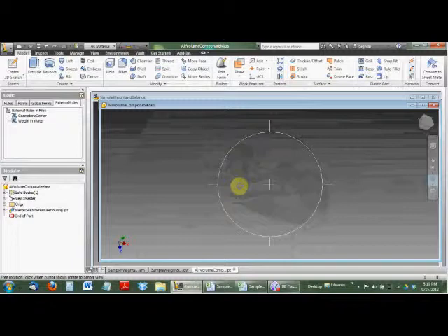And what you do is you have a model of your electronics and your chassis, you have a part model of your cylinder and end cap, and then you actually just take and you intersect those models with some simple shape, right? That simple shape is not the air volume, it's the air volume plus some extra.